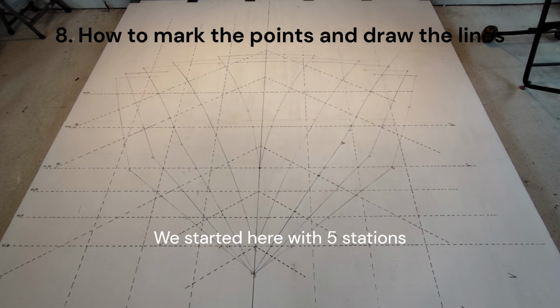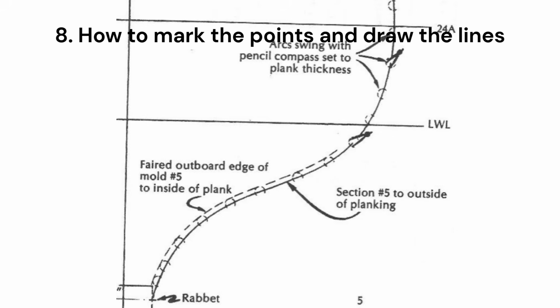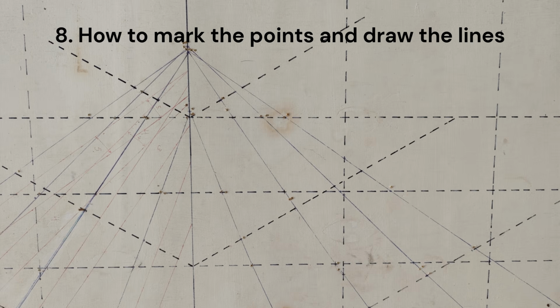If you have chosen to do a separate line for planking deduction, you will need to use another color, for example red. Bud McIntosh's method is to make arcs with a radius equal to the deduction. But you can also mark these pretty accurately by just measuring out perpendicular with a scale. If performed right, the errors will be very small. When performed for the initial stations, it will look like this. Note we have also marked the width of the station frame.